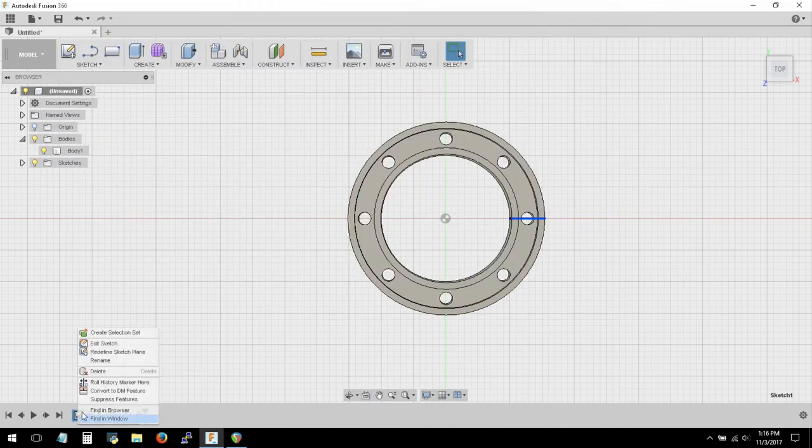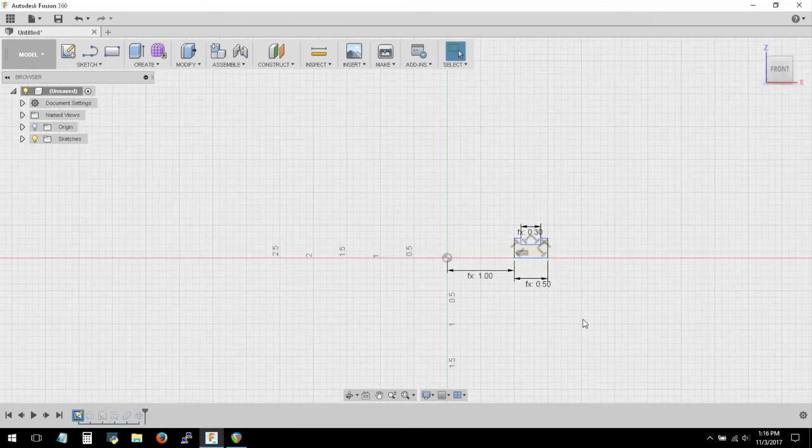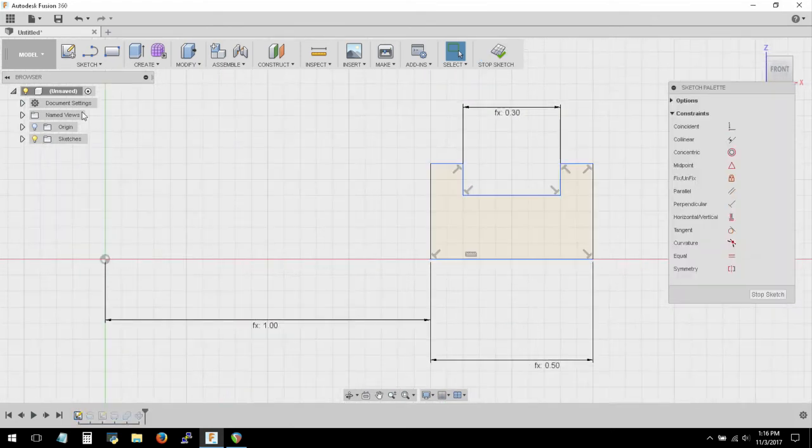Now we're going to edit the sketch here. Zoom back in. Create dimensions. Tray depth. See, and it drops that down however low we want it. But the thing is, you're going to have to deal with that and thickness on it. But you can change it all sorts of different ways. So if I didn't want to do it that way, I could say, get rid of that,